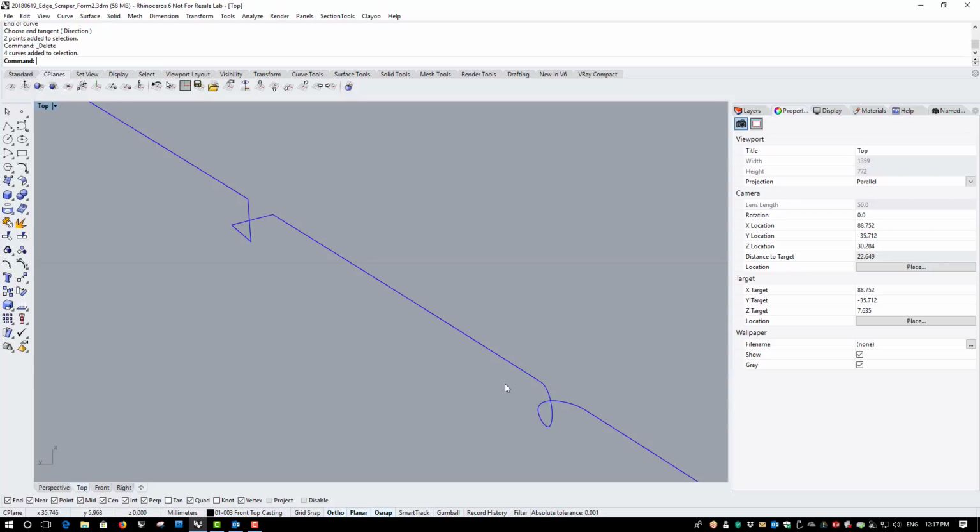Generally speaking, if you can avoid this situation down here on the NURBS volume, then you will avoid this situation on the mesh. And if you see this situation on the mesh, you can generally overcome this by remeshing at some slightly different mesh settings.